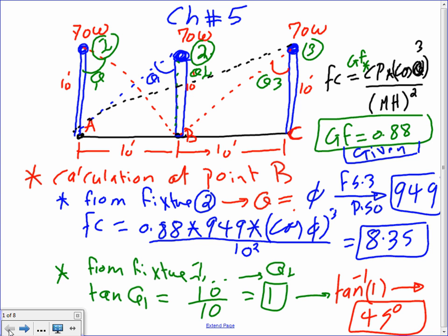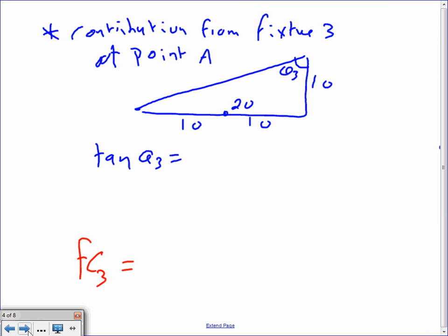Here's where somebody can screw you up. They put this height at 25 feet. If you have the height at 25 feet and this is at 10, now that's what I call a stupid design. You can't use symmetrical then. The nice thing about doing it by hand in the past, guys, is they used symmetrical. Everything is the same, so you do a few calculations and then everything else is symmetrical, the same calculation. Okay, I need thumbs up that everybody understands symmetrical before we move on.